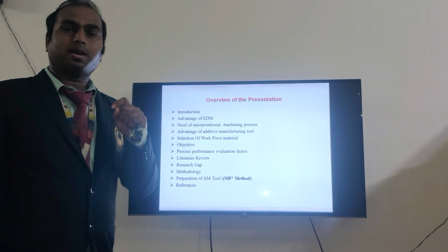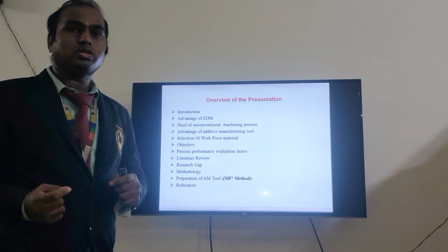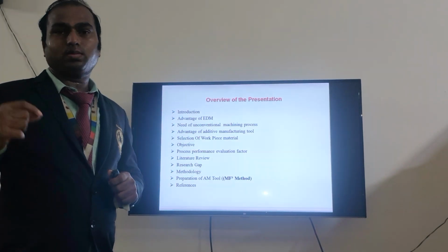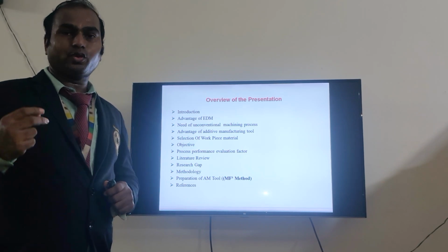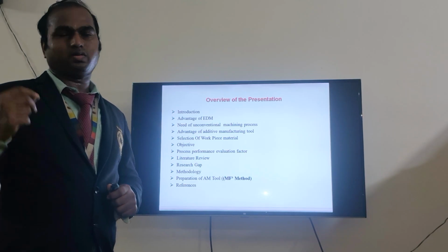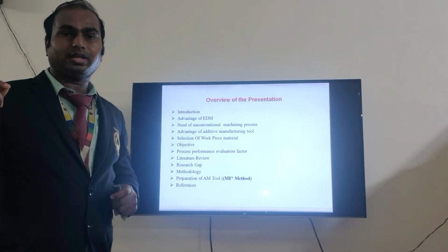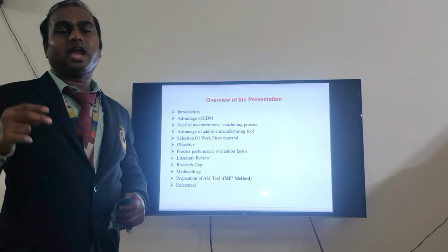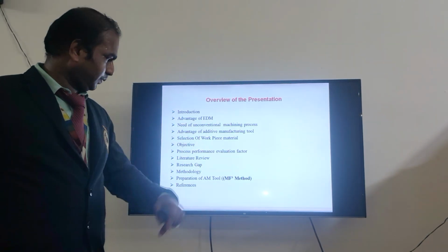The triple M method is the metal fused filament fabrication technique, where we use copper as a filament and extrude it through the nozzle by a special heat addition process. It fuses the filament and prints layer by layer. The normal filament diameter ranges from 1.75 to 2.5 mm. Finally, we are going to optimize the parameters and discuss the results with the references.